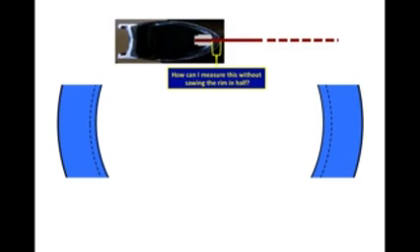Here's our cross section of the rim, and here we see a spoke coming through the small hole through the rim. We see the threaded portion of the spoke sticking into the inside of the rim, and here we see our internal nipple screwed on all the way. Notice that the threads on the spoke go all the way to the end of the threaded part of the nipple, and that the nipple is flush with the inside of the rim. The question is this: how can I measure this thickness of the spoke bed without having to saw the rim in half?